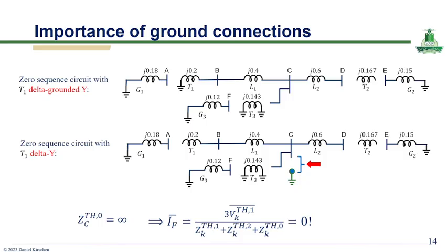the presence of the grounded neutral provides a return path for zero sequence currents, allowing them to flow through the network during ground faults. This is reflected in the connected zero sequence circuit, where all elements, including generators, lines, and transformers, participate in the current path.